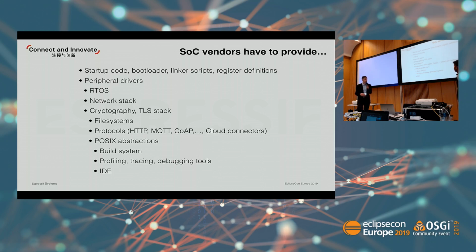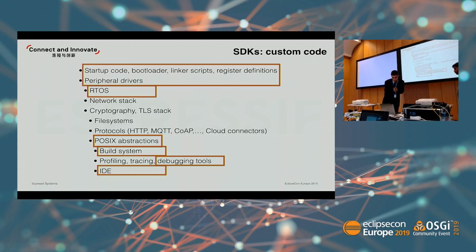And also some things that you typically don't find in semiconductor vendor SDKs. We also provide quite a lot of POSIX abstraction. So you can use pthreads, even though this is FreeRTOS. We still provide a pthread layer, which builds on top of FreeRTOS. This way we, for example, can implement features like C++11 threads. They're typically based on pthreads, so we can support that as well. And some other tools like profiling, tracing, and IDE, which is the topic of this talk.